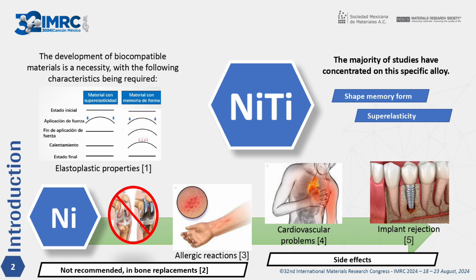It's well documented in the literature that nitinol alloys display the most favorable shape memory and superelastic properties. However, they have been demonstrated to contain nickel, an element that is toxic to the human body. The utilization of nickel in the formulation of alloys for bone replacement applications is not advised, given the potential for adverse effects resulting from the release of nickel ions. Such effects may include allergic reactions and cardiovascular problems, among others, which may result in the rejection of the implant